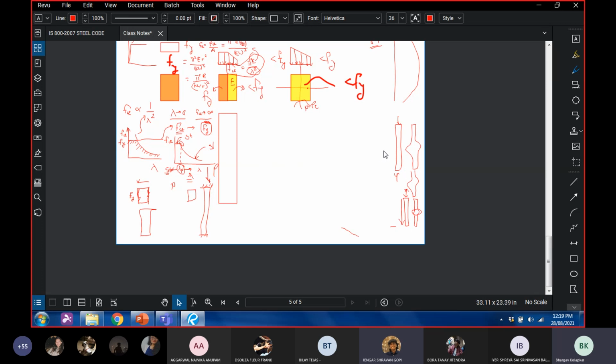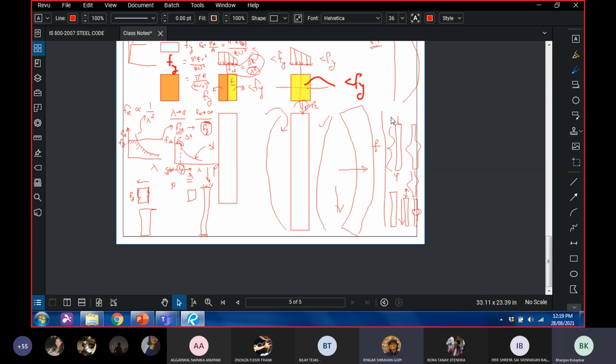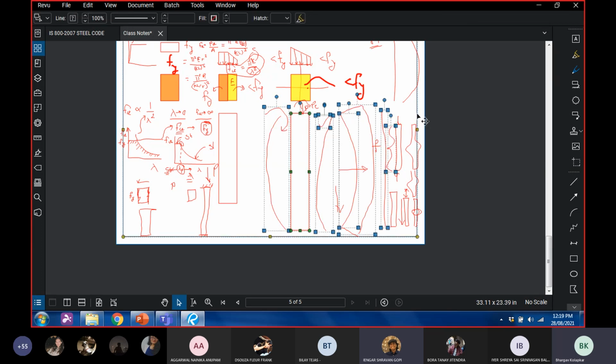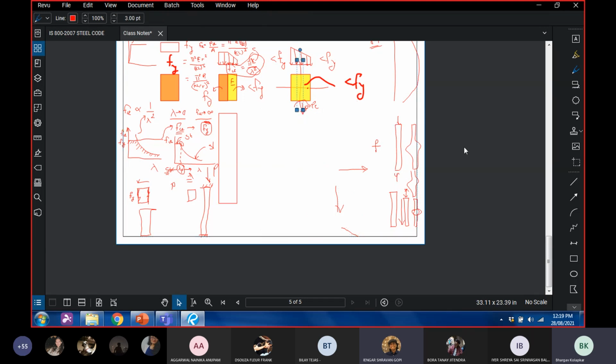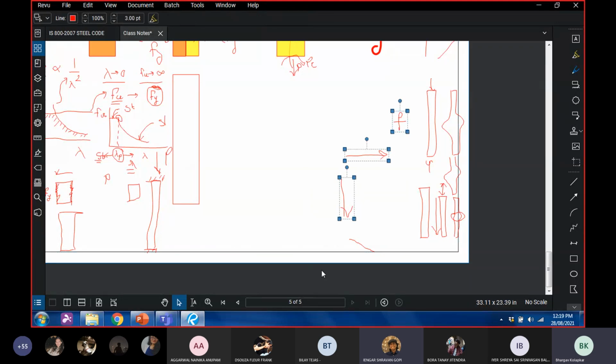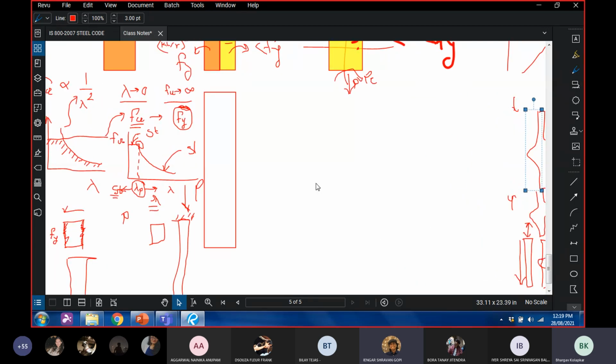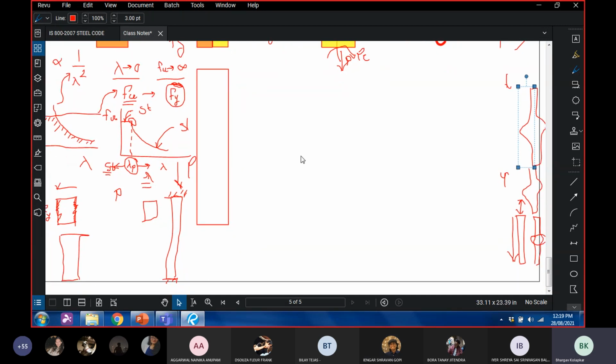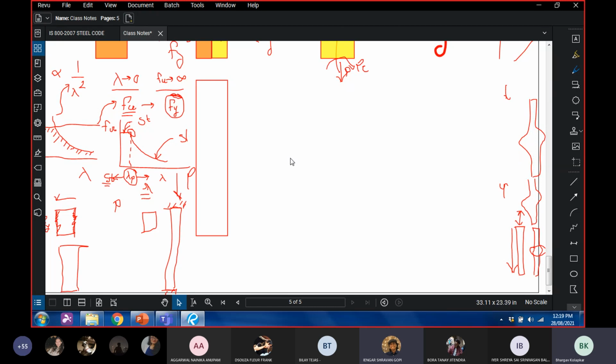Yeah. But when we are talking about these columns in theory, we aren't considering any loads other than the structural load, like wind load and earthquake load, right? We're just looking at the dead load, so to speak. No, we are looking at all loads. So P is the maximum of all the loads that are occurring. So it's the unified vector of all of them. Yes, it is the governing load combination.